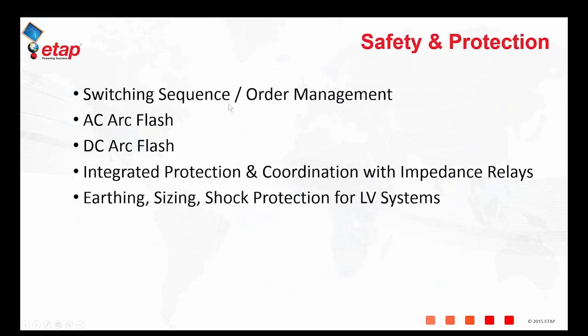On the safety and protection side, you can also utilize the switching sequence management, where you can understand the effect of different breakers opening and closing in the system and its impact on the network, AC and DC arc flash from the substation perspective, protection and coordination, as well as earthing and shock protection for the low voltage system.